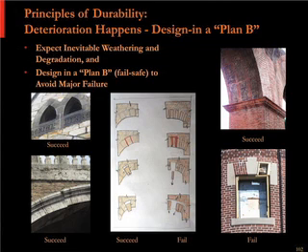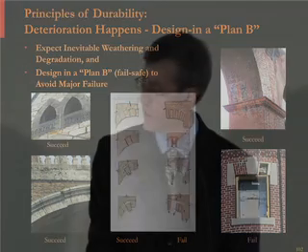Similar idea in stone and masonry arches. So the Roman arches, you typically see a very tight joint. If they use stone, it's usually wedge-shaped. If they use brick, the joints are very tight, as you see at the upper right. And they may even be wedge-shaped, but even the rectangular, they basically meet brick to brick at the bottom. So the bottom line is, if the mortar erodes, you might get some shifting or displacement. So in the sketch in the center, you see that mortar erodes in the red line, the wedge drops a little bit, but then a new point of stability is reached, and you don't have a catastrophic failure of the arch. That's also what you see at the lower left photo where that's actually happened.